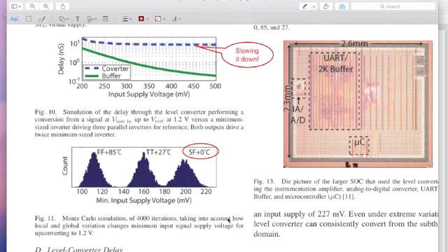So it might be overly pessimistic to assume that the supply voltage will drop by 10%. But nevertheless, whatever amount it drops by, you use that value on the low side and the higher value on the high side, in addition to slow and fast and the lowest temperature. That will be the worst case condition, and if you can ensure that your level converter works there, it's functional, then you have basically a good design.